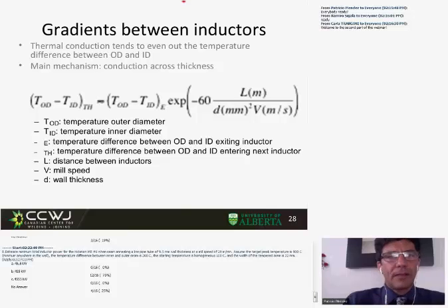Or conversely, on the outside we can have the right temperature, and that's what we're measuring, and we're all happy, and on the inside we have not reached full austenization. If we do not reach full austenization, we're not completely erasing all the bad microstructure that came from welding. Welding has a very fast cooling rate and is full of hard phases.